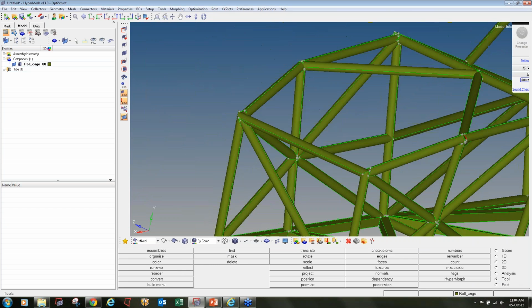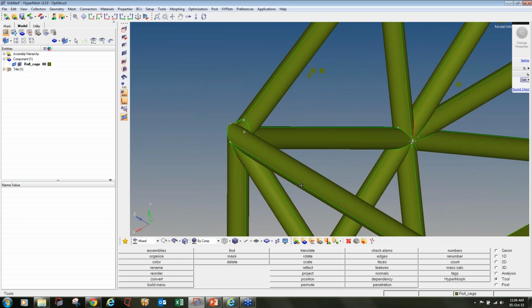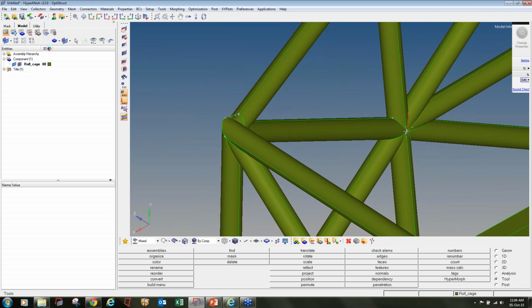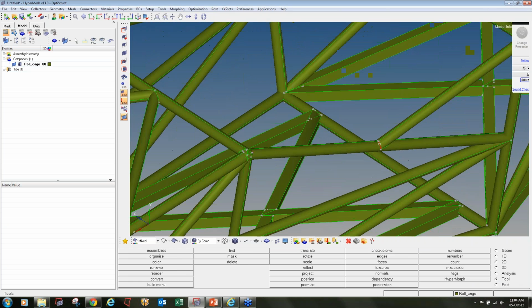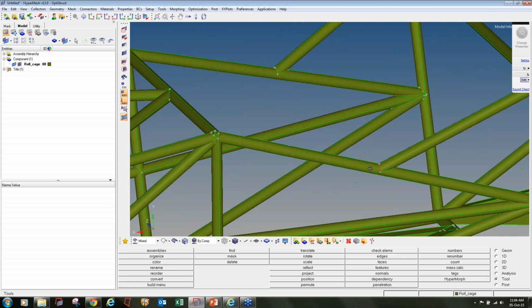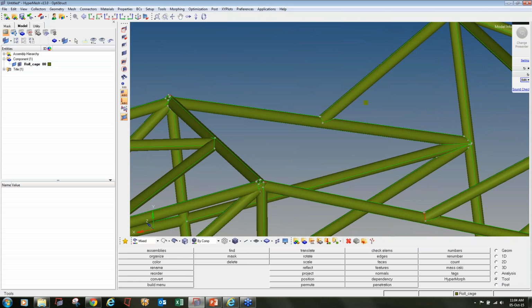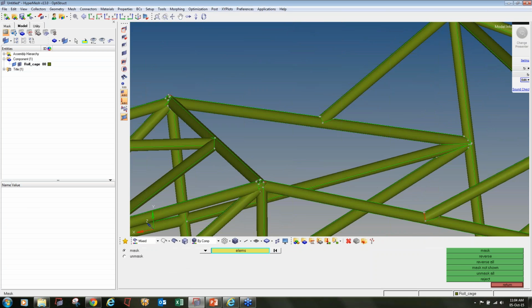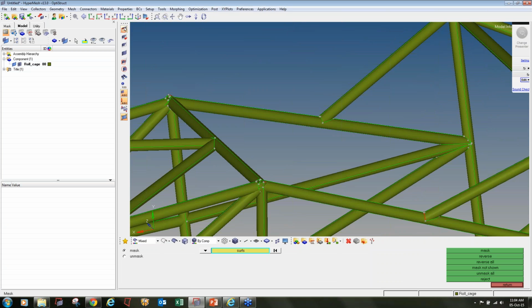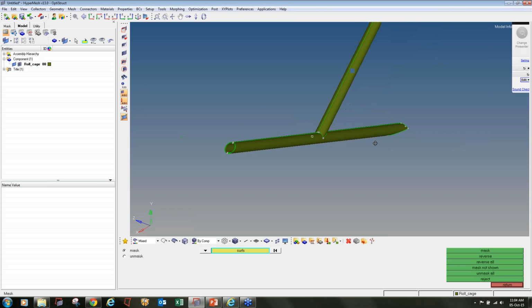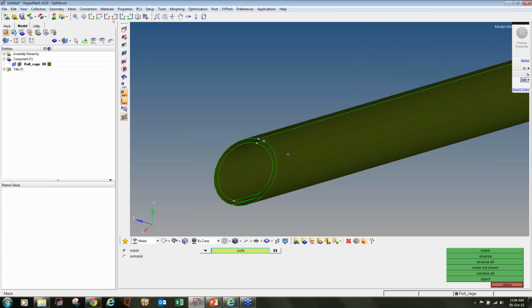First of all, I will show you how to edit the geometry for a single joint, and similarly you have to do it for the rest of the joints. So I will show you one of the joints where I will do the geometry editing. In the same way you have to do it for all the joints. I will go to the mask panel. From this icon I will go to the mask panel, select the surfaces and say mask, reverse. So this is a 2D surface geometry.